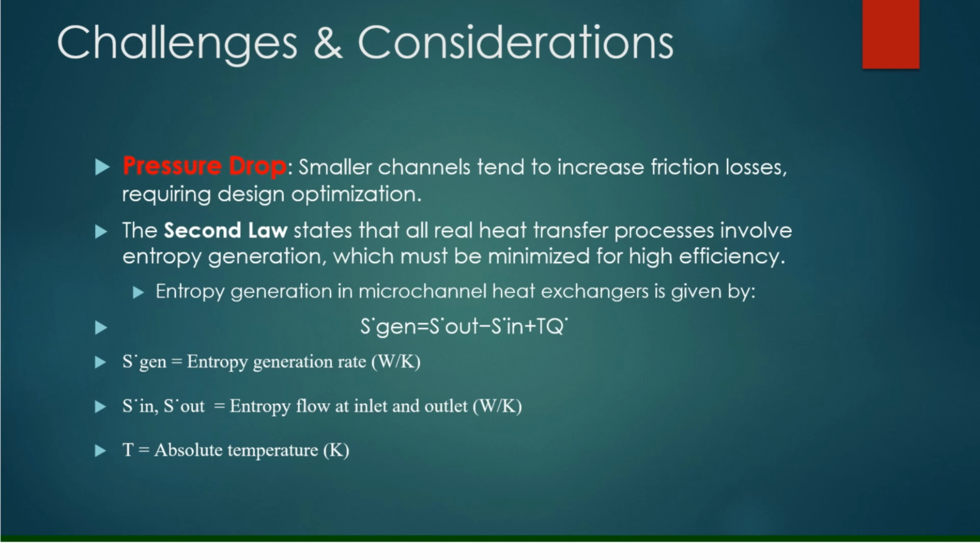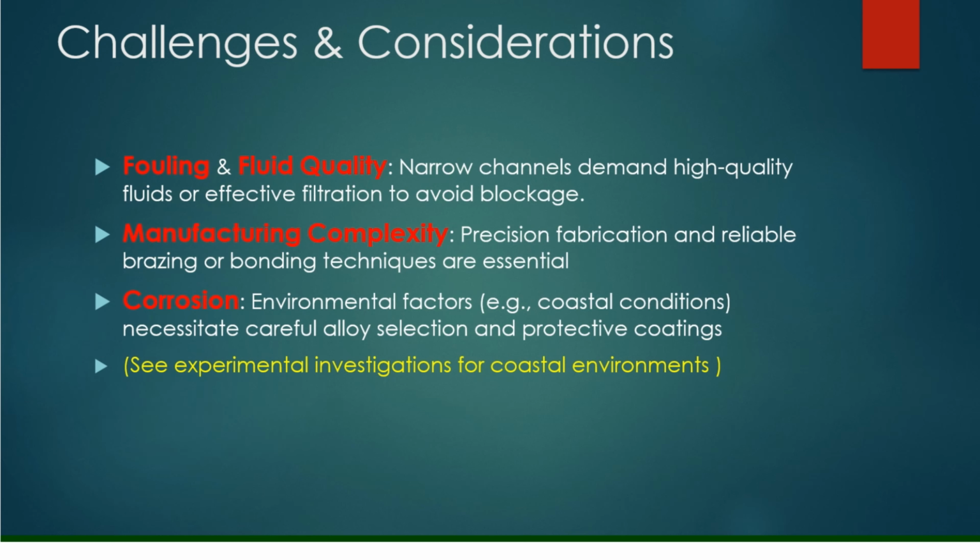And I will explain this whole second law thing, I'll come back to it. So there is fouling and fluid quality. Narrow channels demand higher quality fluids. So think of it this way: if you have a tiny straw, even a small particle can clog it.